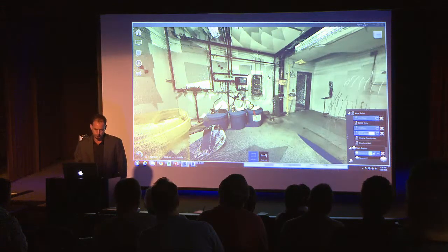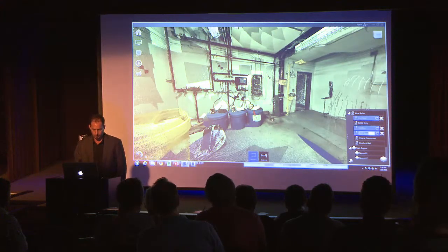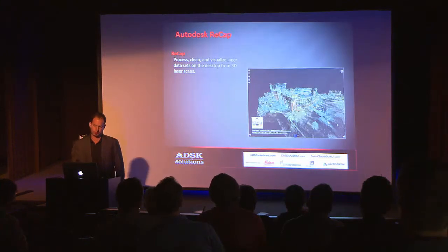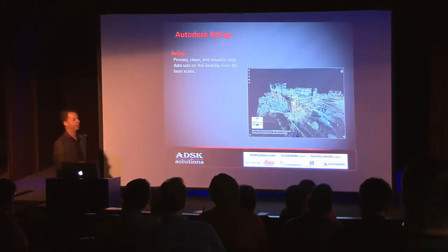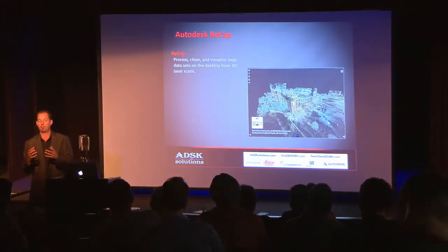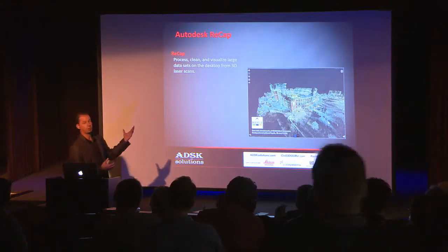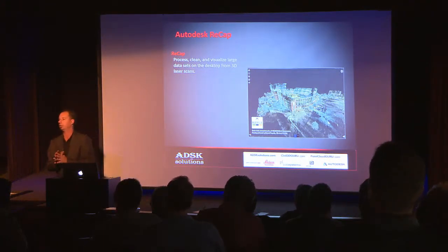Cool. Any questions on Recap? Cool. Again, it's a free download for Recap. Everything you just saw there, so the Recap Pro is putting the scans together, and then once we had them together, that's just using Recap. So if anybody gives you a deliverable of point cloud data, you can load it up directly into Recap and do everything I just did, except for create that puzzle.